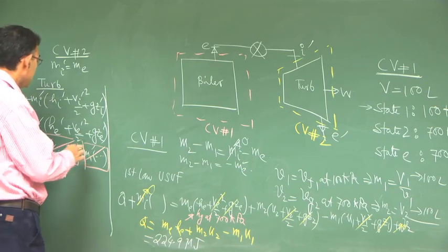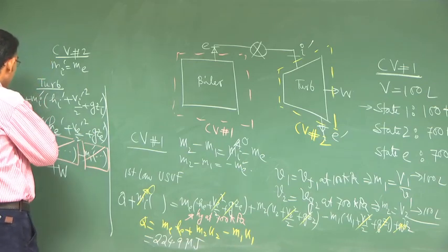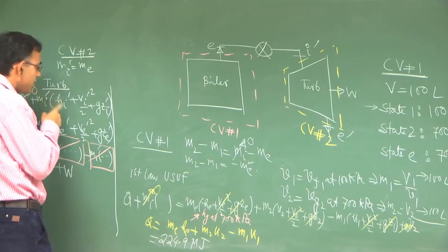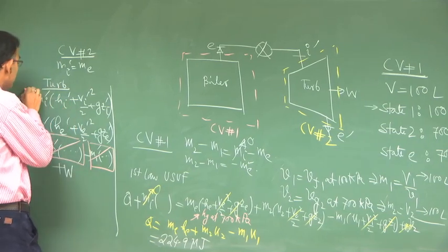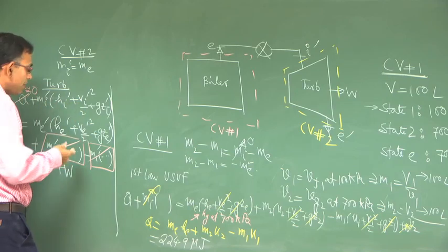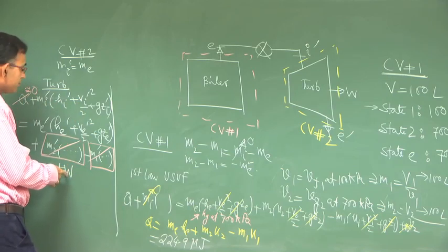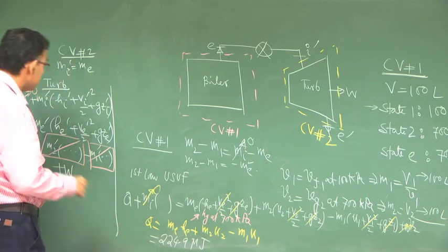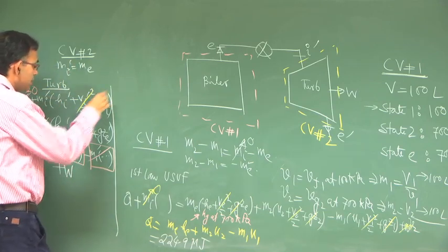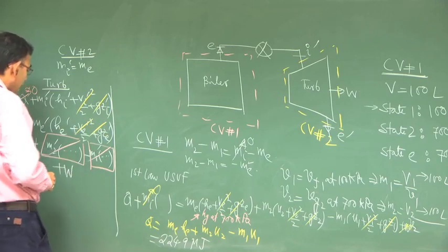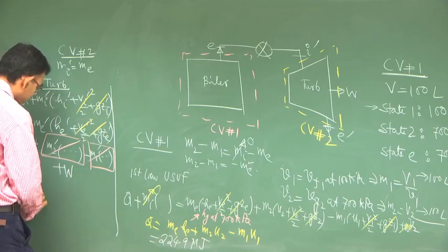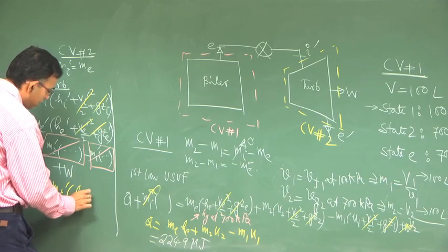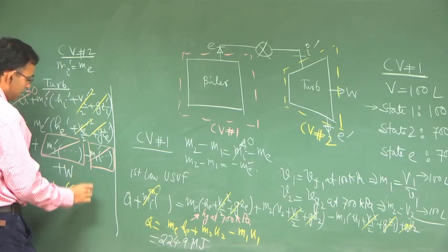So, this change is 0. The turbine is primarily for work done, so heat transfer is neglected unless stated otherwise. It is approximately 0, not really, but as compared to the work it is not very significant. You can neglect the changes in kinetic and potential energy. If you do that, then W will be mi prime into (hi prime minus he prime).